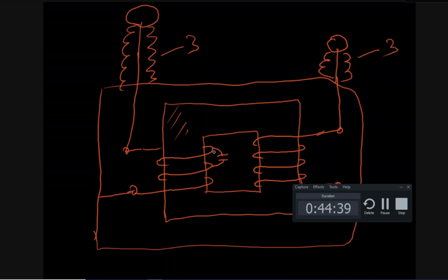Whenever two metal electrodes are separated by a certain distance, and if there is a potential difference between them, that will act as a capacitance. Therefore, there will be capacitances between the turns also, and inductances and capacitances, and the wire also has resistance. Therefore, each winding is a ladder network like this.